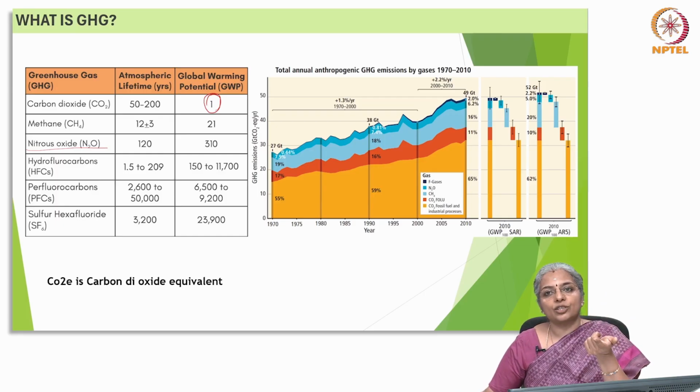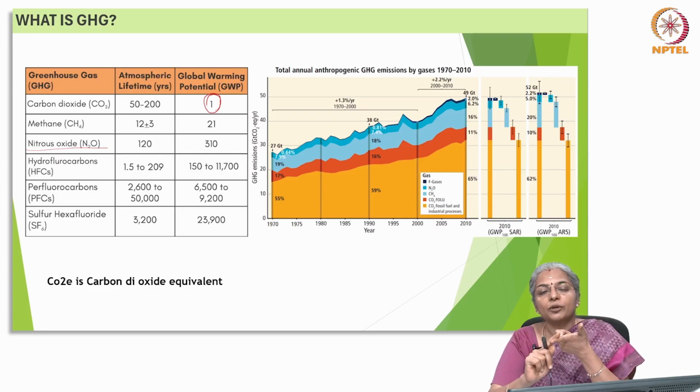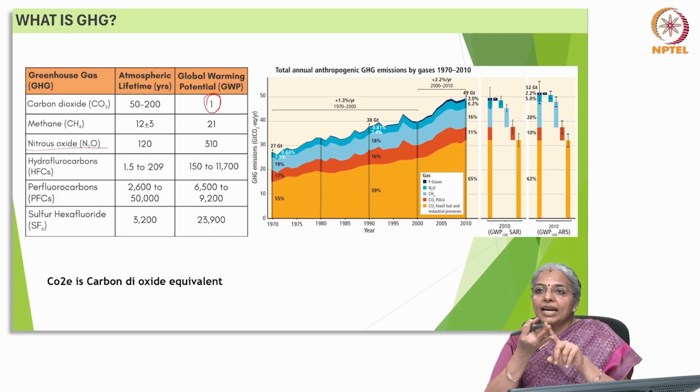Embodied carbon is actually the sum of greenhouse gas emissions released during extraction of a raw material or the ore, transportation of the ore to the manufacturing plant, the process of manufacturing, transport of manufactured goods to the site, the actual construction process, the maintenance and retrofit or renovation of the building, and end of life of the product system.